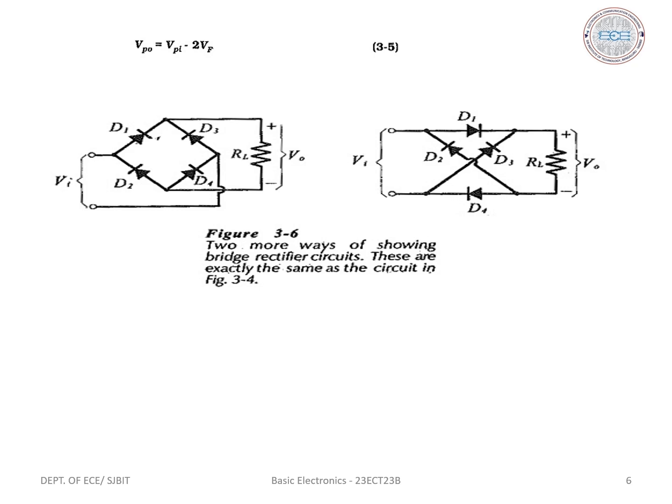Hence, the capacitor takes more time to discharge. During this time, D3 and D4 will be reverse biased and in the non-conducting state. Therefore, the only discharge path for the capacitor is through the load resistance RL. So this is how the bridge rectifier works.